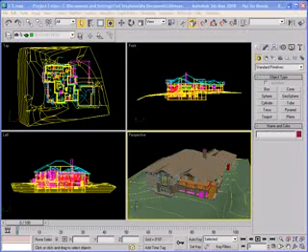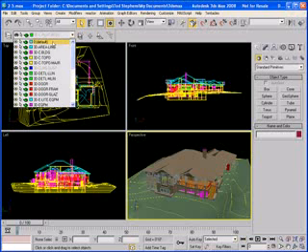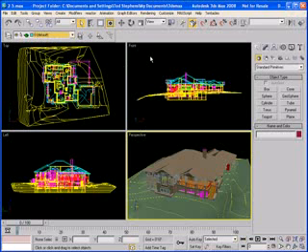And just one last thing to remember, under my layers here, I'm going to change the layer off of that current layer there. That layer was turned off. So if I had added objects, they would not have shown on the screen. So it's just a good habit. I went back and changed that to the 0 default layer. Now if I'm working with objects, typically you're going to add a layer and then add an object, but just a good habit to get into to switch off of a layer that's turned off. And that'll do it for this video.